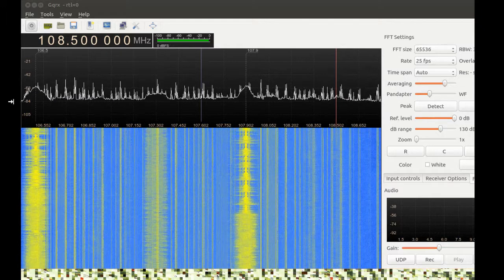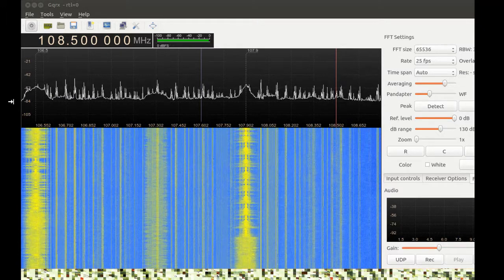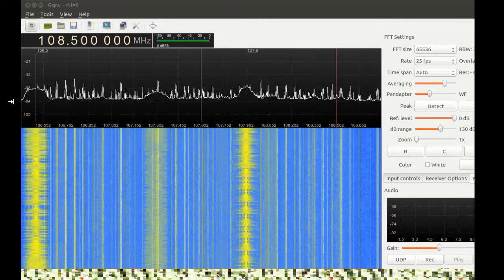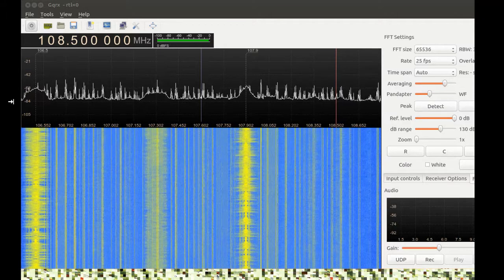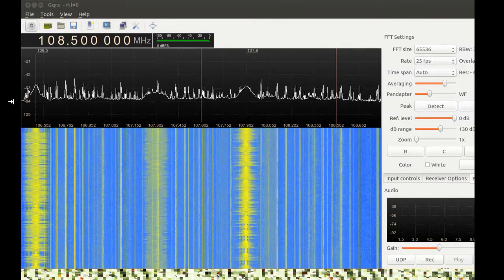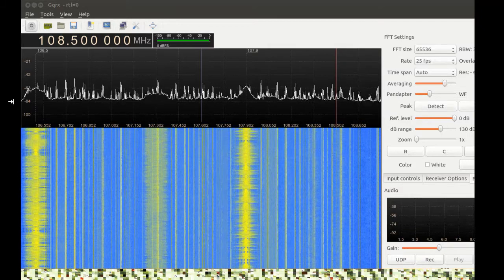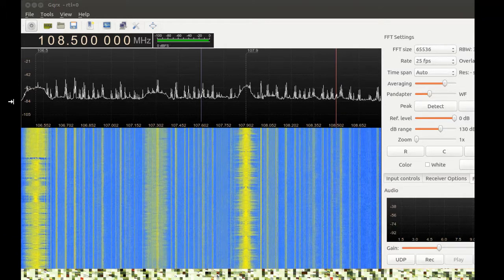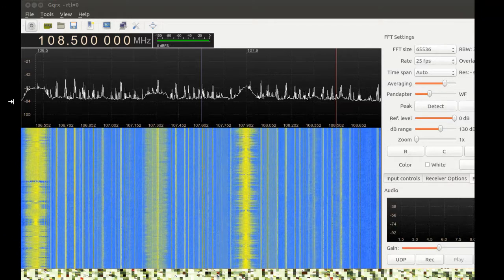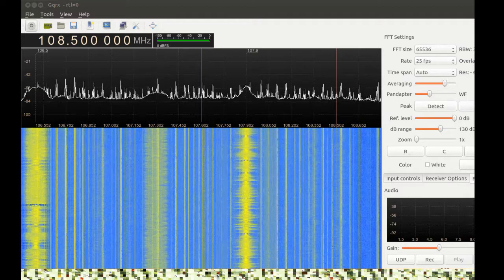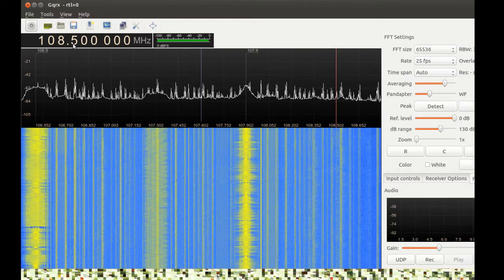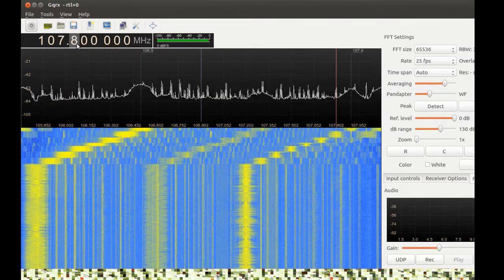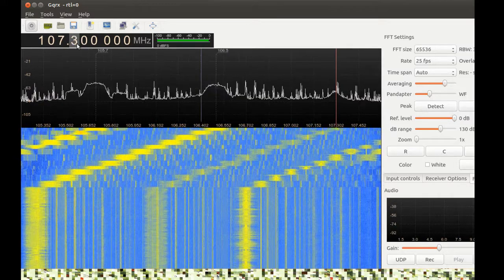Alright, is everyone done bookmarking? Who is not done bookmarking? Alright. So now there's a new FM station. And by the way, it's not going to sound good unless you use wide FM mono to decode it, because I can't get a stereo flow graph working in GNU Radio. So how you find that is you just keep going down, same process as before, but instead of stopping at the bookmark, you just keep going down. And eventually you'll find a new station that's not bookmarked.